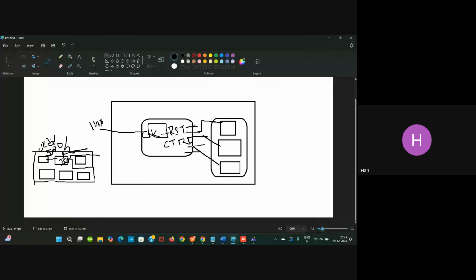See, depending upon chip specification, there will be certain module codes which get instantiated within the entire design. And what RTL engineers do is they will have a clock reset control in the design, where they take a common clock input from the overall input, and it is further divided into smaller frequencies like 500, 125, 200, something like that.